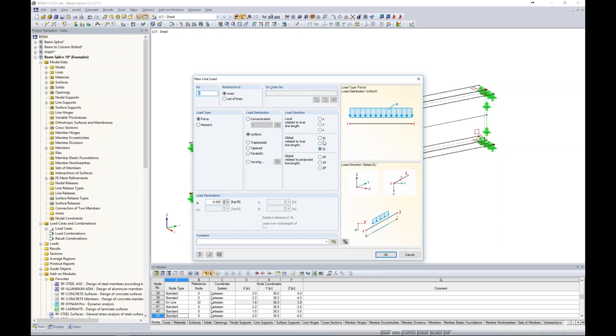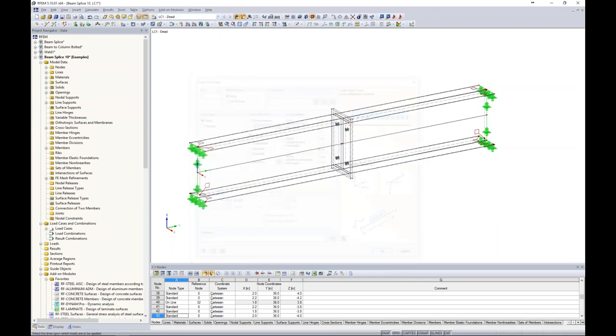So with a line load, we simply specify the load direction in the global ZL direction and give it a magnitude of -50 kips per foot. I click OK, and then I can click to the top of that beam member over here on my left. I think it's perfectly acceptable to not have symmetric loading for this particular connection, but to really see when we have unbalanced loading. So I'm just going to apply my load to my left-hand side and leave the right-hand side without any load except for self-weight.